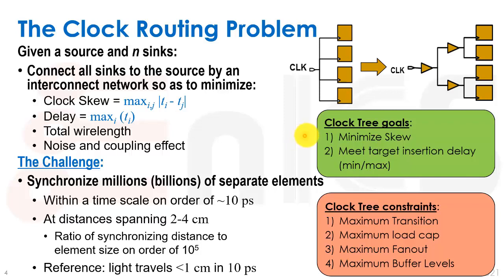When we usually discuss how we do clock tree synthesis, our goal that we always focus on is to minimize skew. So the basic assumption is that during synthesis and during placement, timing optimization post-placement, we had an ideal clock, and we tried to meet setup constraints. We tried to meet the target frequency or the highest frequency possible by optimizing, upsizing things and changing our logic and so forth, everything we discussed in previous lectures.